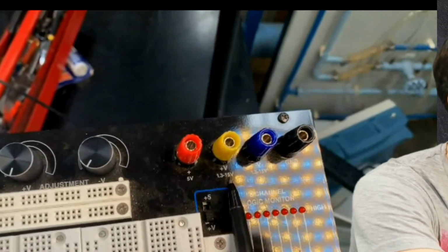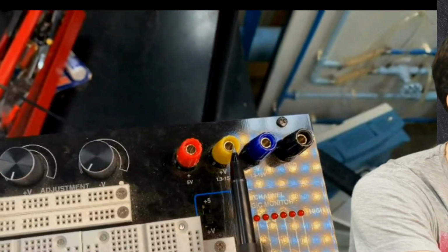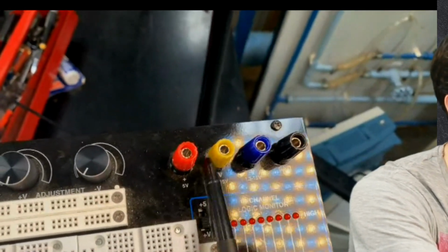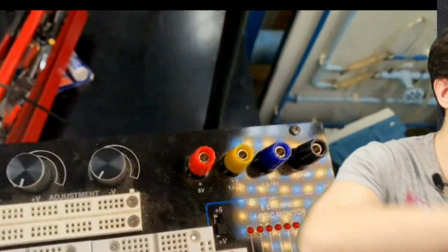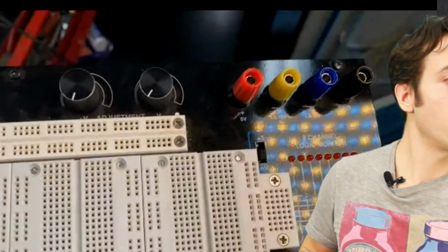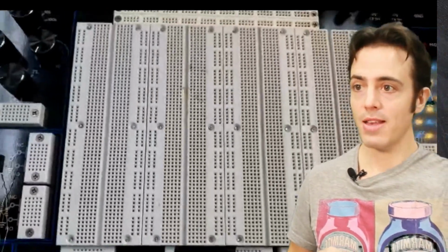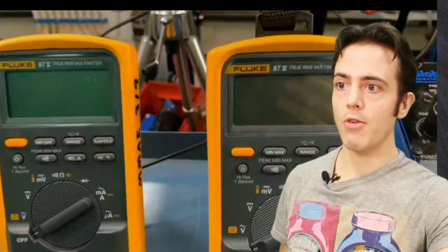If we're going between them, we'll have a theoretical minimum voltage of 2.6 between these two, all the way up to 30 volts. So we can then use those as power supplies for the actual circuit that we're going to be setting up, and then we'll put those resistors in, and we're going to measure the applied voltages and the current through them